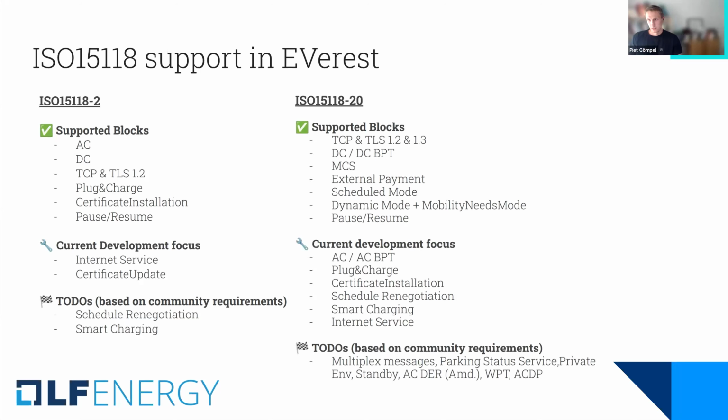For the ISO 15118-20, we also have support in EVerest for the supported blocks listed above. TLS 1.3 is new. We have started with DC and DC-BPT support, MCS, external payment, scheduled mode, dynamic mode, and mobility needs mode, and also implemented the pause resume feature.